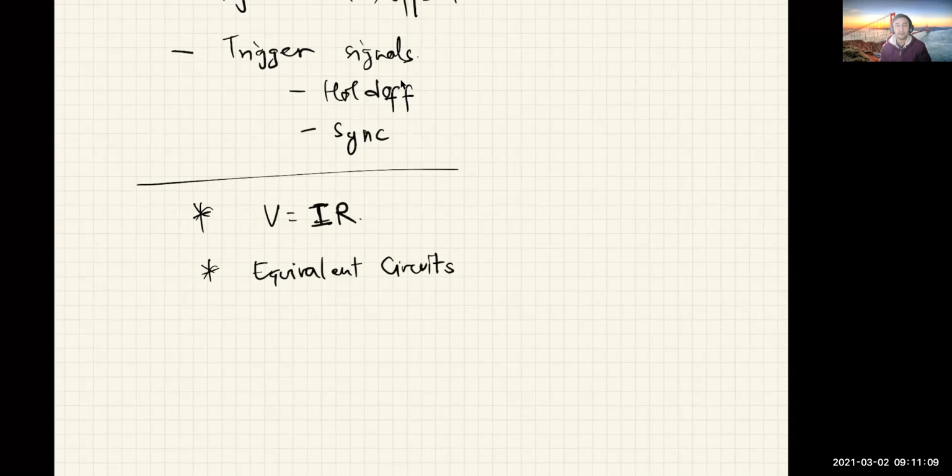And that's a Thevenin equivalent model circuit. And also, you can model it with a simple current source and a parallel resistance, which would be the Norton equivalent circuit. You learned about how to measure these Thevenin and Norton parameters, and you applied those skills in Lab 5 as well as in the lab practical.